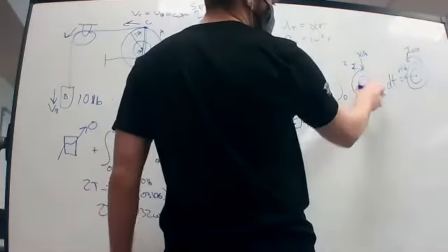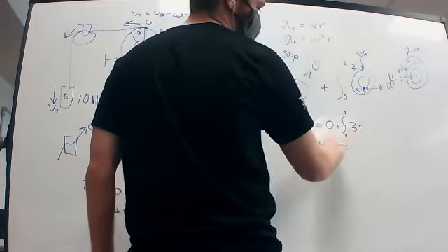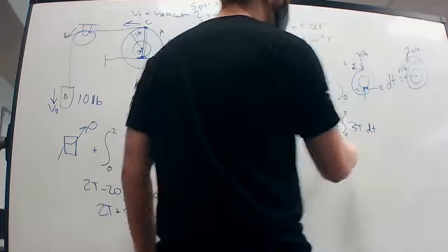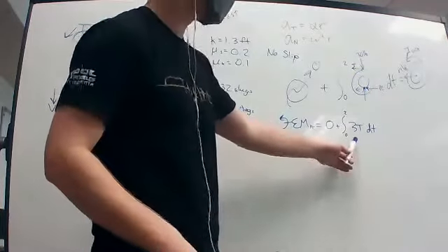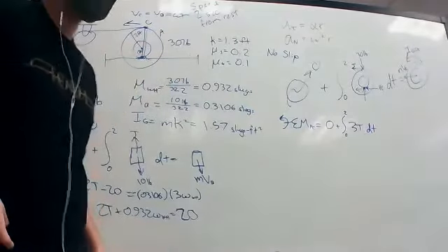That's it for this piece, because the normal force, friction, and weight are all going to pass through the point of contact and therefore not be included. So 3t dt, and reminder that big T and little t are not the same. Big T is tension, little t is going to be time.